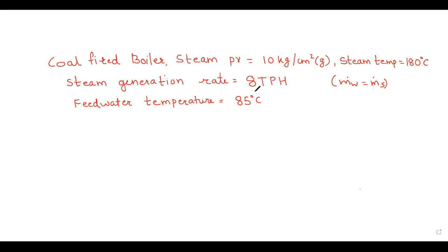If they don't have the panel, if it is a very old boiler, then we need to actually put in instruments and record these readings. Then we need to know the quality of the coal, and by quality I mean using the bomb calorimeter. You need to take a sample of the coal, and as a boiler auditor, you need to note down the calorific value. Let us say that the calorific value of the coal is given in MKS units. It is 3200 kilocalories per kg.